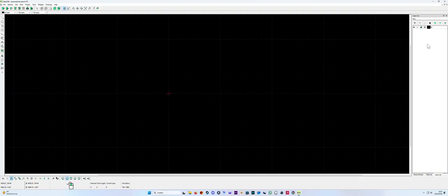Here on the right you see the layer list. What's the layer list? The layer list is the list of layers you want to use for your drawing lines. I click this one here, the 0. You can put a different name, but let's say 0. You see the layer name 0. Then you can see the color is black and white, so you're drawing black lines.